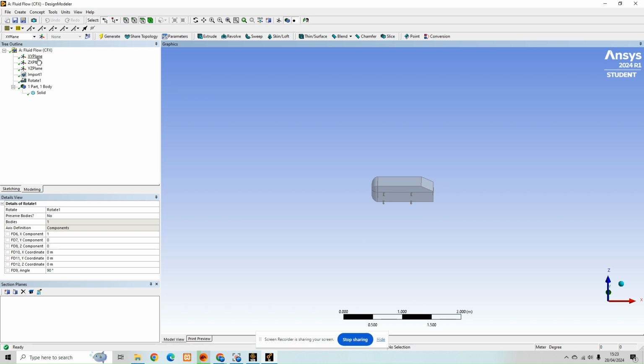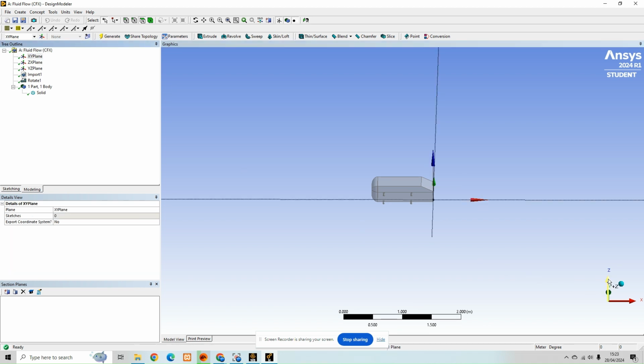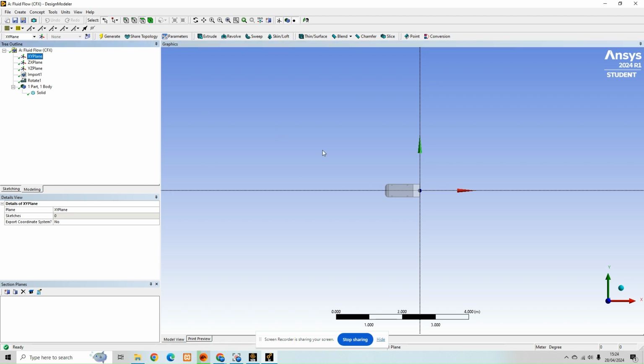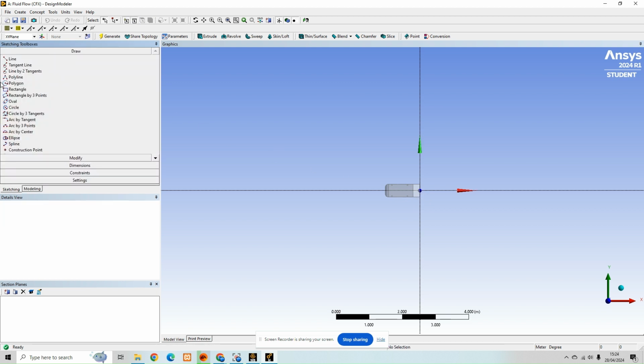So we can begin by building our domain. I'm not that fussy that the front end's not sitting on the origin. This is for demonstration, but normally I would make sure the front face and center line are at the origin point. So begin by sketching our computational domain as we always do, a couple of heights upstream and bias downstream.